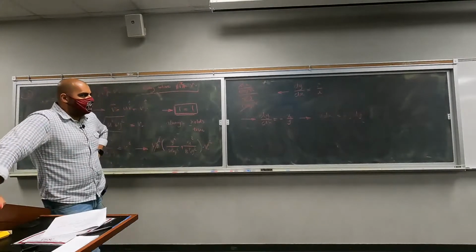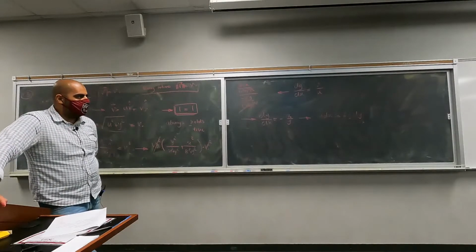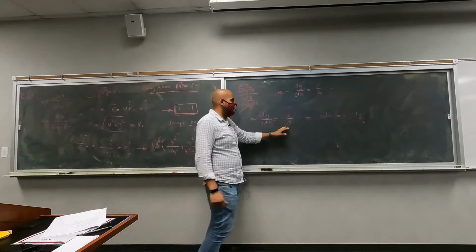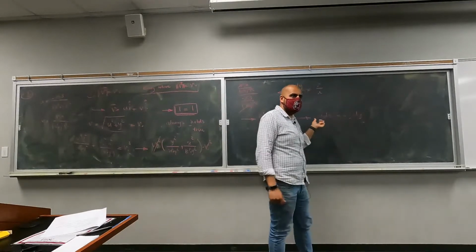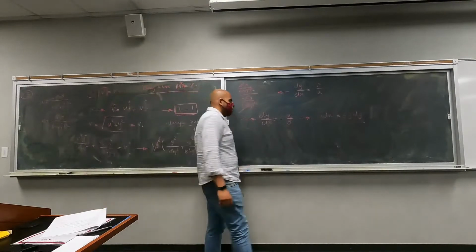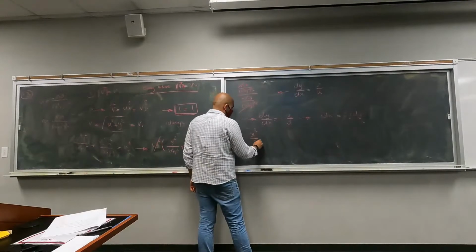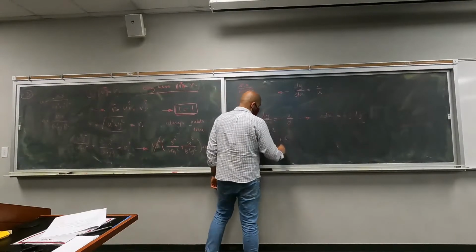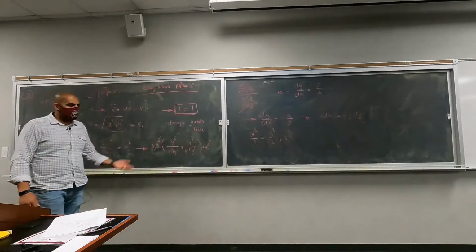Okay. Can we take the integral here? To find the equation of the streamline, this was the first step: find the slope of that streamline, then simplify your problem. You take all of the y's to one side, all of the x's to another side, and then you take the integral. What will be the solution to this integral? It's going to be x squared divided by 2 equals negative y squared divided by 2 plus a constant value. This is an indefinite integral, so you have to include a constant.